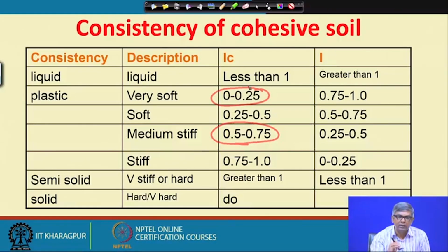From that equation it is giving you the line, and if the value is above that equation line, that means it is clay, below the line means it is silt. And again, from the range of liquid limit I can decide which is intermediate plastic, high plastic, medium plastic or low plastic. So, these are the things we can do. Now we can go